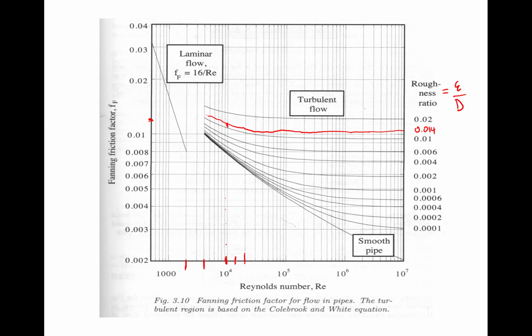Also, we have a roughness of 0.000297, which is somewhere around here, right? In between this line and this line, it would be an extra line that will go through here. It really doesn't matter because we're trying to get up here, and you see that all these lines eventually converge into almost the same place, right? So when we get here, we are somewhere around here, right?